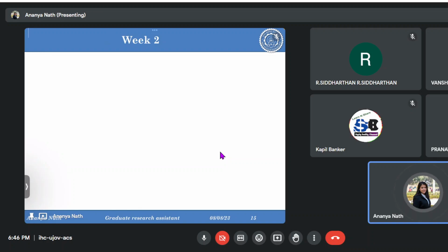We raise the temperature of that particular alloy, and then we hold it for a particular time interval. At the holding time, what happens is called aging. That time is definite hours or days. We hold the material at that particular temperature, and in aging this sort of mechanism happens, in which strains are induced, due to which we restrict the dislocation movement. So what happens is, if we draw the stress strain curve,